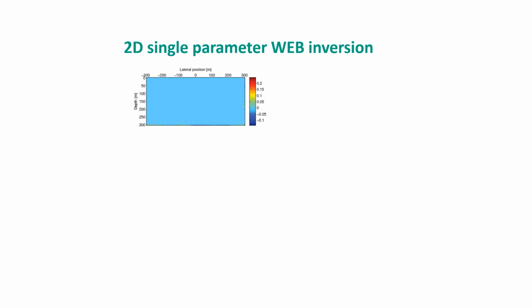So the very first step of the inversion, it's a linear inversion. So you see here, we have a homogeneous background model. That's all the knowledge that we have in the beginning. And then you apply a linear inversion to your seismic data. And the result that you get is the following. You see that the base has been imaged quite properly. You see that the roof has been imaged quite properly. But still you see quite a couple of side lobes, and also the vertical pillars, they are completely absent.